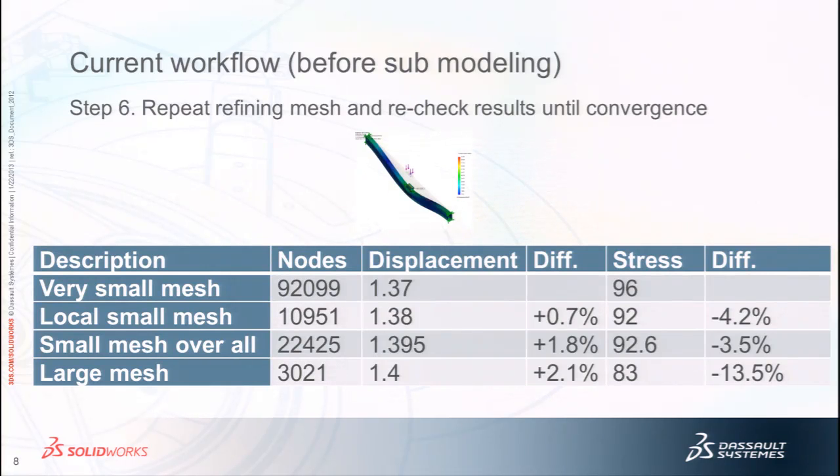So the user went back and said, okay, I've not got my result yet. He does a lot of things. He can either just refine the mesh at a local region, refine the mesh for the entire model, or identify areas which are changing and areas which are not changing, change the mesh and do it, or use adaptive and static analysis, which will do that for you. It will change the mesh based on where the results are changing, and then try to refine it.